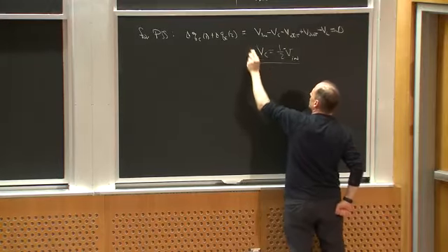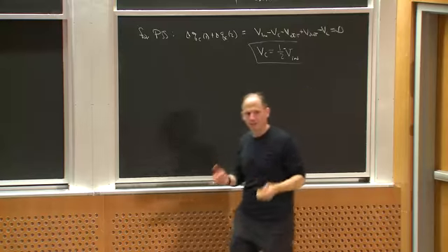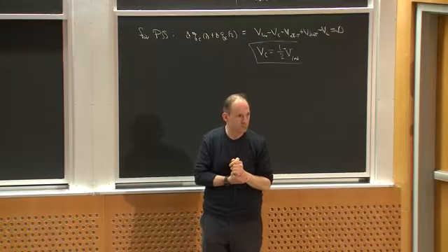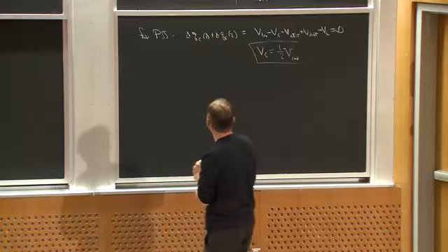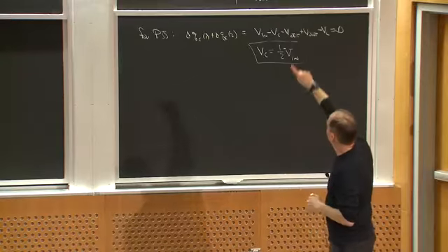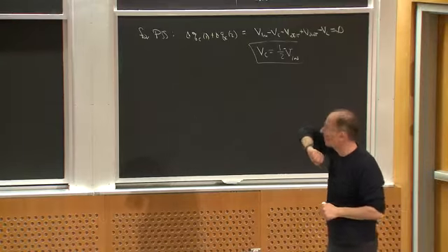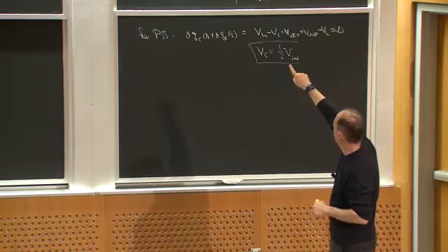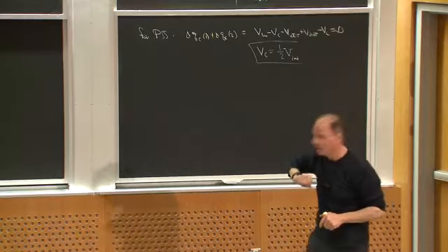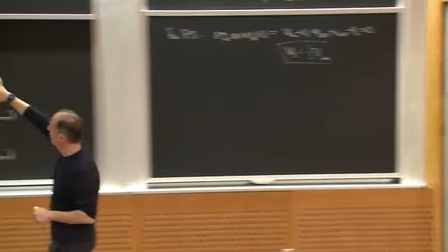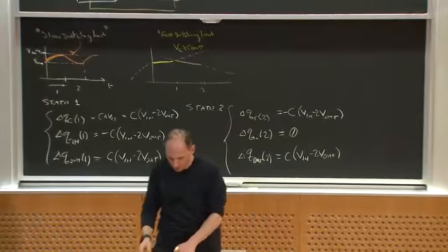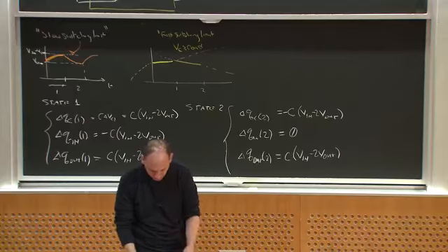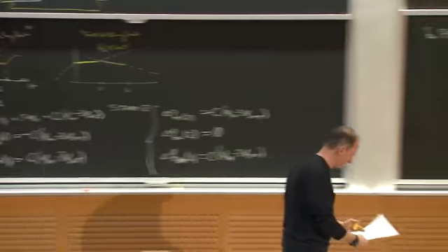So in periodic steady state, I'm going to be charging and discharging the capacitor, but it's going to sit at an average value of half V in, okay? I can then plug this value back in, and I'm running out of time here. I can plug this back in and find Q out 1 and Q in 1, right? I can do the same game I do over here. And if you do that calculation, it's pretty easy.